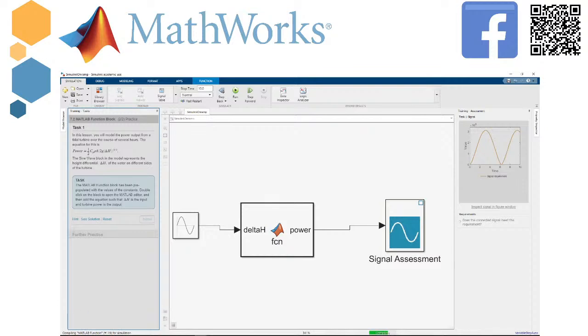Okay. Add the sine wave to the model. Double click on the block and change the sample time parameter to 0.5. Note that the icon changes to indicate that it is discrete. We change the sine wave, which is an input, from a continuous system to a discrete one. Okay, so we can just zoom in.